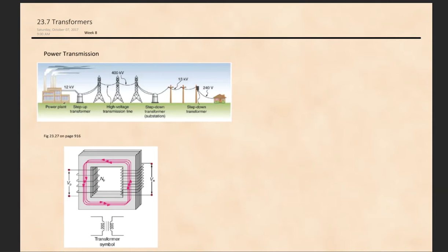So there's a generating station somewhere that produces electricity through some mechanical process, whether we're boiling water or letting wind blow across fan blades. There's some process that's turning a shaft that's connected to a generator. That shaft is attached to coils of wire inside a magnetic field, so as it rotates, it generates an EMF. That produces a voltage which causes current to flow.